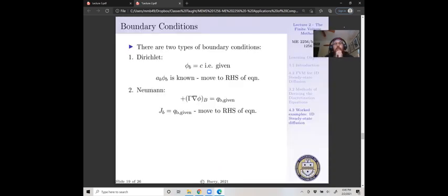Now, as I mentioned, we have our two types of boundary conditions. Dirichlet, where we have a constant conserved quantity, i.e. a constant temperature. And Neumann is new, but you see it quite a bit when you're prescribing a heat flux and waiting for that temperature to evolve, because you can't simultaneously provide a flux and a temperature.